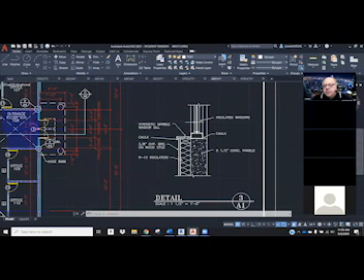So we've got an insulated window, there's a concrete panel, and then we're going to what's called fur out the wall. Now, for residential students, we do this in basements. When we do a basement wall, it's pretty much the same type process, except the basement wall is made in a form or a mold to get the wall, and then we'll build a wood wall in front of it so you can hang things and put insulation in there.